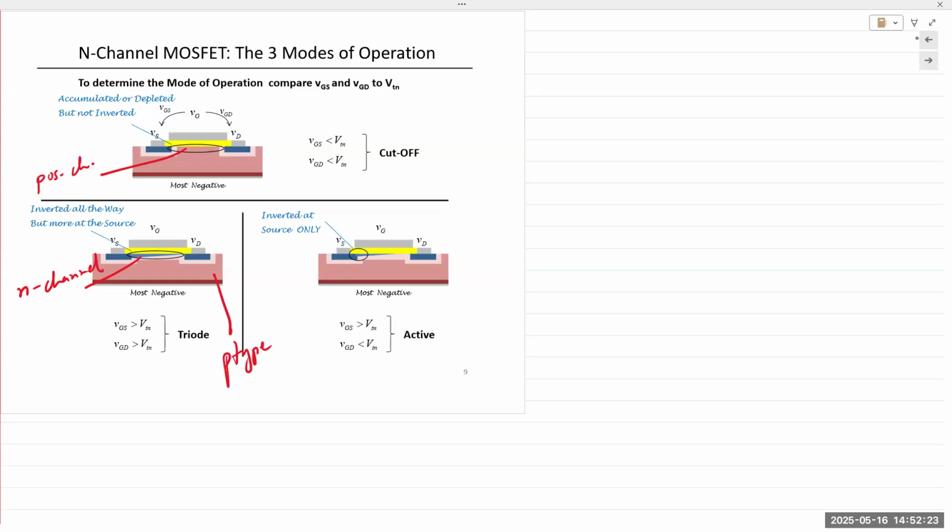Well, but then it wouldn't be called a source. It would be called a drain. Well, that's why it's a symmetrical device. If the physical dimensions are exactly the same and the doping profile is exactly the same, it would be a completely symmetrical device. But again, in real life, in many of the transistors that we buy, whether discrete or integrated on a chip, the body is connected directly to the source or to the drain so that it's kept off.